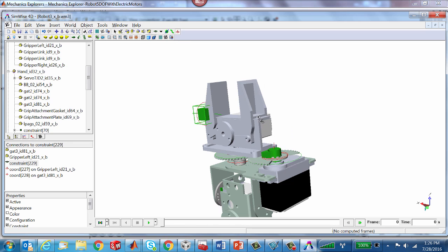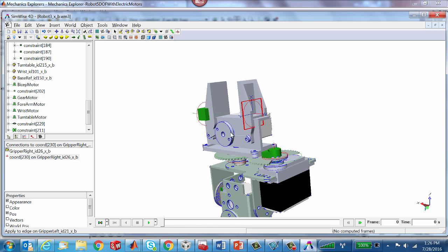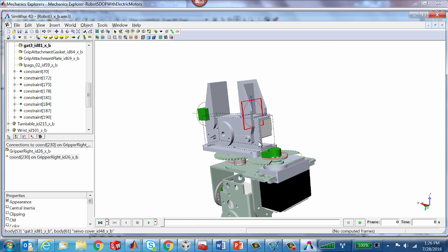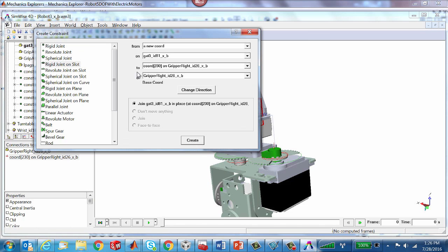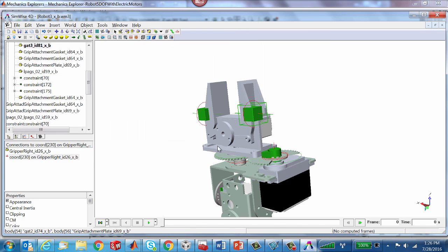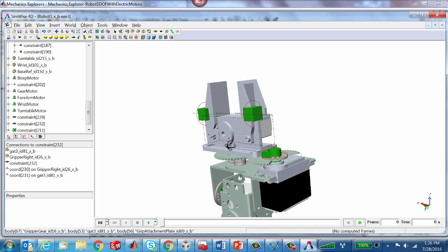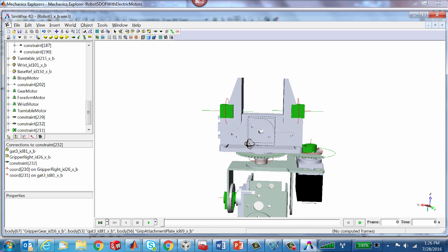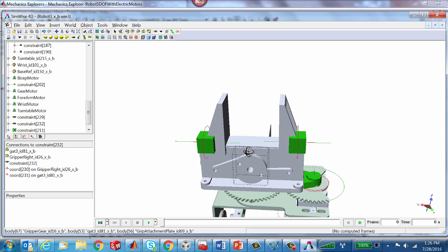All right, and so let's put in a frame on this side. Okay, and we place that frame on that surface like that. All right. Again, that z-axis defines the direction we need, and I will right mouse click, create another rigid slot, and I kind of got that. At this point, we're getting real close to being done. All right. And what we need to do is set up this crank slider mechanism.